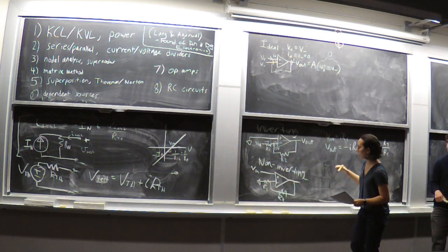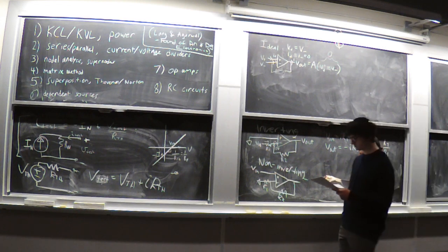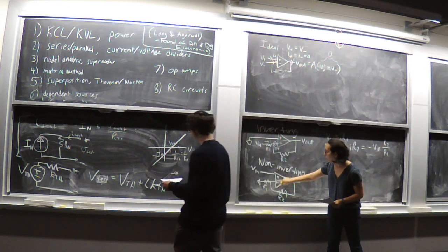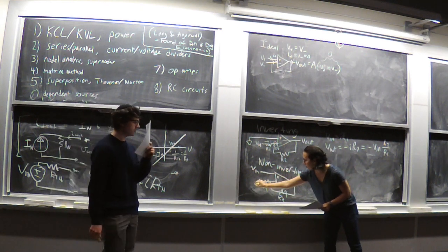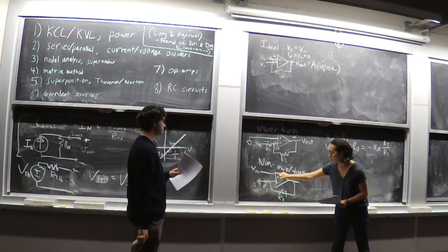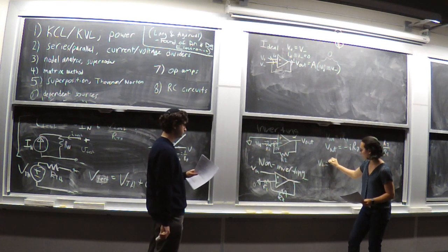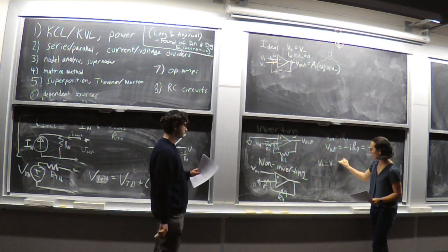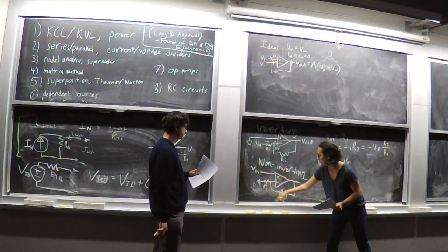In this case, the quick way to see if your circuit is inverting or non-inverting is to look at where ground is. So in this case, we have this location at 0 volts. V in is at the plus terminal, which means V plus equals V minus under our ideal op-amp assumption, which equals V in. And now if we look at this component,